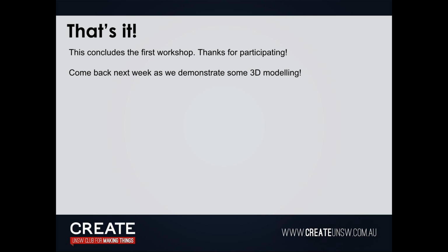Okay. Now we do. What's it called? It should be mirror, shouldn't it? Oh, you can't mirror a face. You can mirror body. A mirror body is different, right? There we go. Bodies. Select the object. Then once you're done, you select the mirror plane, which is that. You hit OK, and you get your 2 halves, right?